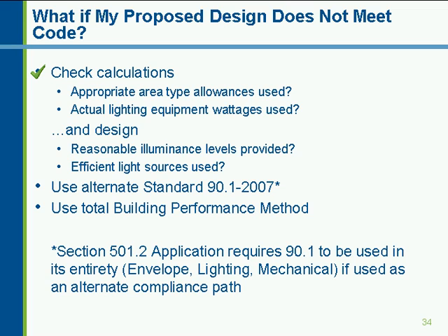You may find in a lot of your applications that your places are overlit. This is not necessarily a fault anywhere, but it's commonly done. You want to look at whatever recommendations, such as the IES site level recommendations, and make sure that you are on par with what you actually need and not more than you need, because if you are lighting to above typical recommendations, which is what the code is based on, you will find that you're going to have a lot of trouble complying with the code.